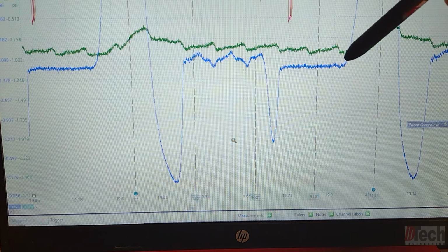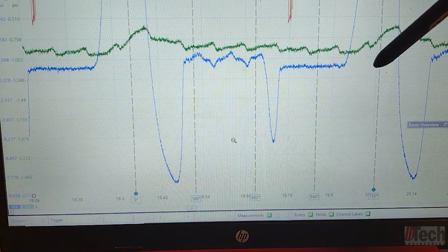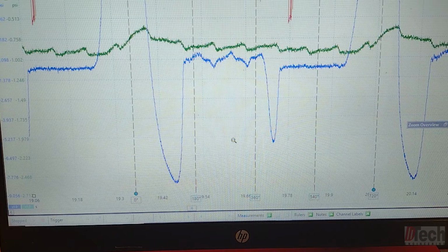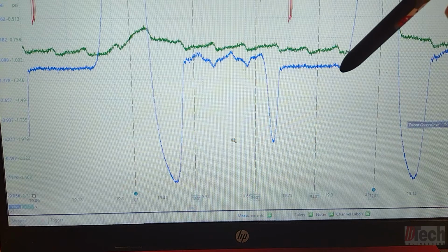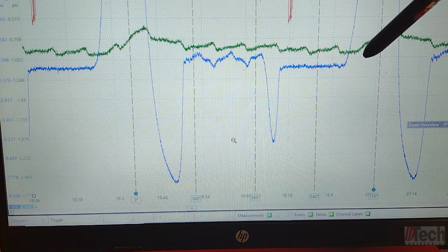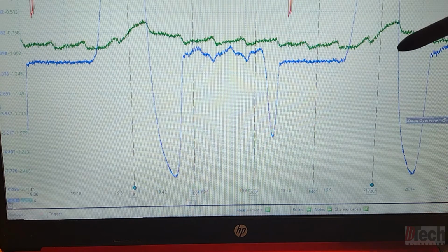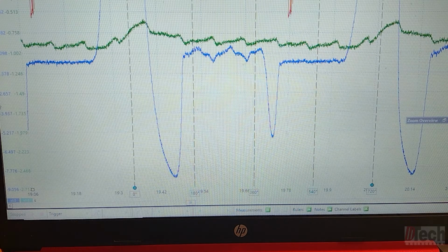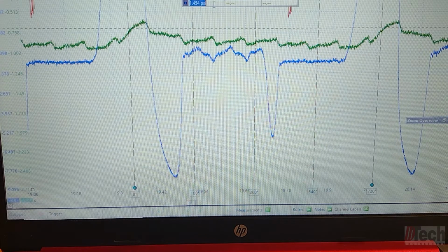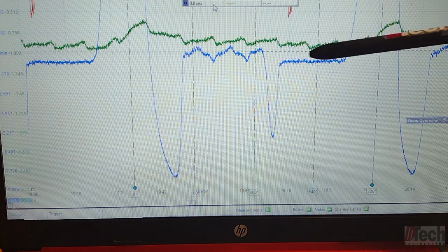And what I mean by that is we know the intake valve closed here due to the piston already traveling upward. Pressure changes in an upward direction at that point, which means the intake valve had to close, and now the piston continues to go up. Now I'm going to concentrate and mark off some points here in this region of compression from cylinder 8, just to see what relation is there during the faulted situation. I'll get my 0 point, basically atmosphere. So that is that line there.